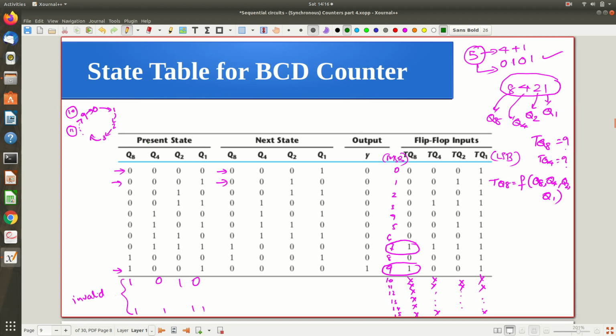What we saw is the BCD counting, the binary coded decimal counting, or decade counting is another name. It's just an up counter, but not like the ordinary up counting where it goes through all the possible states. Here it will go from 0 to 9 only, right? So 10 different states it will count, and after that again it will reset to 0 and continue up to 9. So now some of the states are invalid, and we know how to eliminate some of the states. Now the question is, can you eliminate some of the states in between? Here 0 to 9 is still continuous, right?